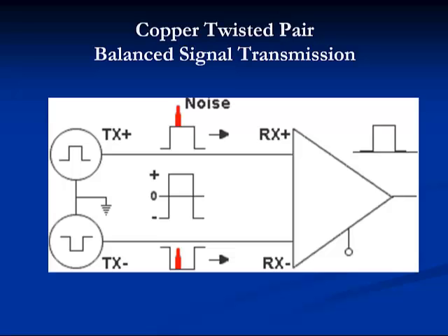Twisting the two conductors of a pair around each other couples the energy out of phase. That's electrical torque and cancels the electrical field. The result is reduced transfer of signal, but the twist must be symmetrical. For example, both conductors must twist around each other, not one wrapping around another that's straight, and two adjacent pairs shouldn't have the same interval of twists. Why? Because those twist points become convenient signal transfer points, sort of like stepping stones in a stream.